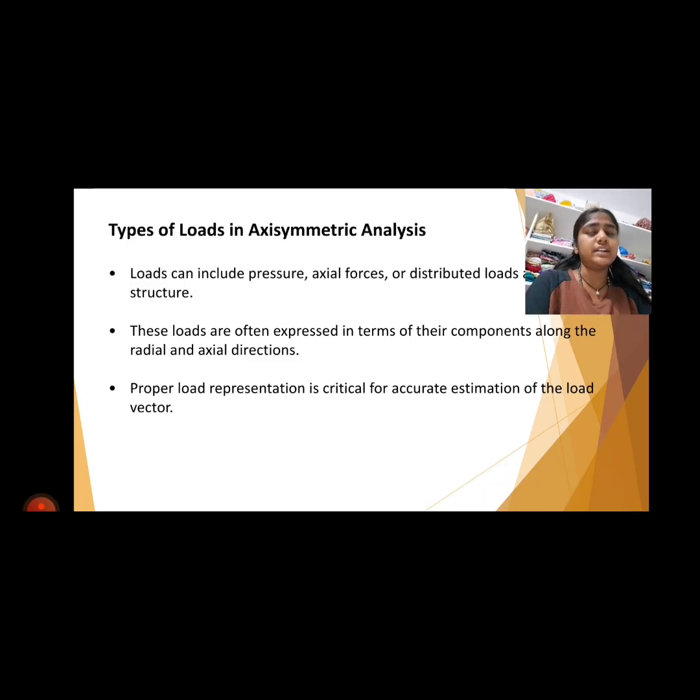Estimation of load vector. The load vector represents external forces acting on the structure. In axisymmetric elements, loads must account for the circumferential effect due to revolution. The types of loads are body forces, surface tractions, and point loads. First one, body forces, due to gravity or centrifugal effects, act throughout the volume. Then coming to surface tractions, pressure loads and distributed forces on boundaries, and then point loads, applied at specific nodes, less